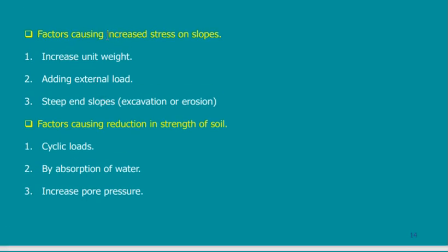Factors causing increased stress on slopes: increased unit weight. If I increase the unit weight of the soil, then the weight will increase. If I add external load, it means that the weight will increase. If I make the slope steeper, this will induce more driving force on the slope. So these three things increase the stresses on the slope.